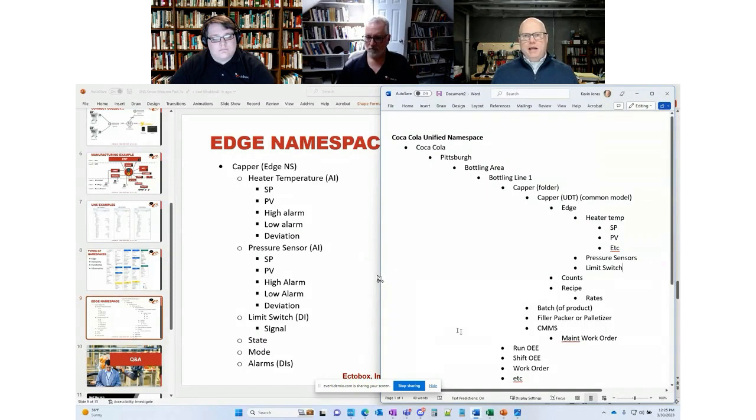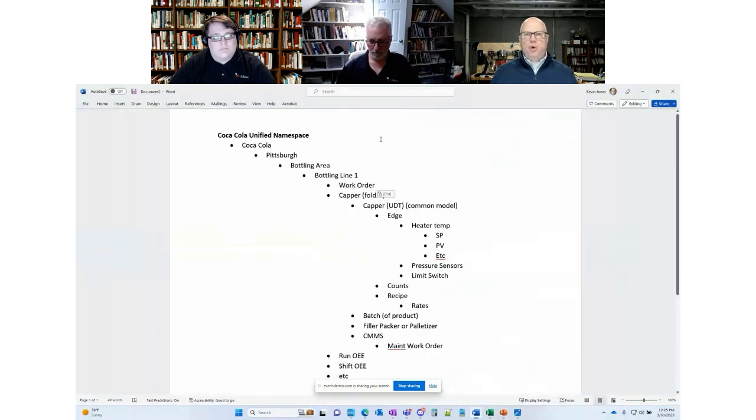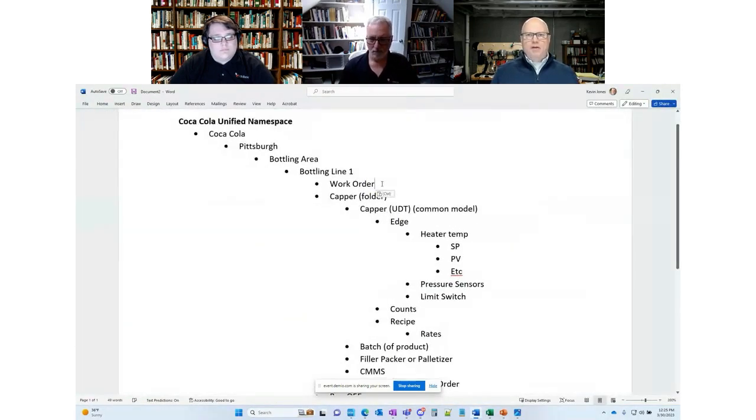Now, I realize in this example, sometimes you'll be finishing off one work order and starting a new production run on a cell, but for all intents and purposes, within ISA 95, that work order really exists at the line level. So in this context, this is the work order that is currently in production, not necessarily all of the work orders that are available from the ERP. When we have what's commonly known as a work order table, that's more of either a site or an enterprise type model.